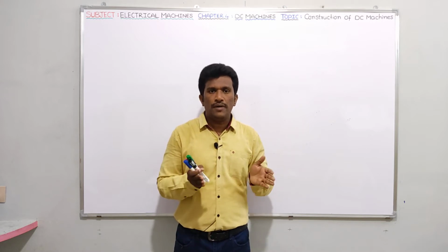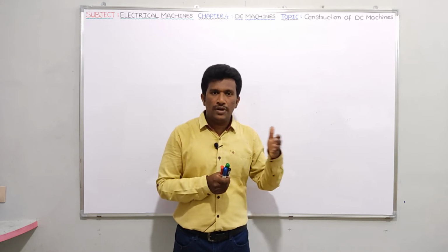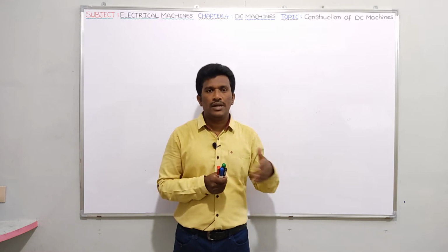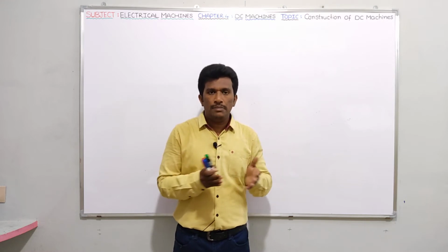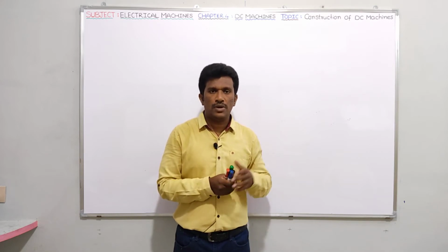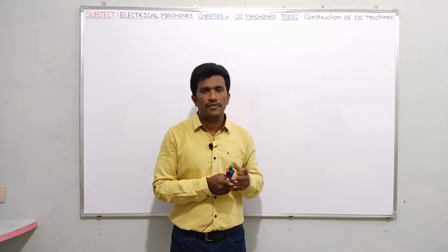And if you compare number of turns, series field winding number of turns will be lesser than shunt field winding number of turns. And if you compare MMFs, shunt field winding MMF is more than series field winding MMF. That was the conclusion regarding field winding.